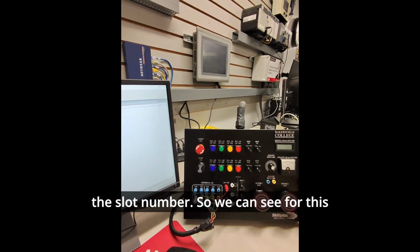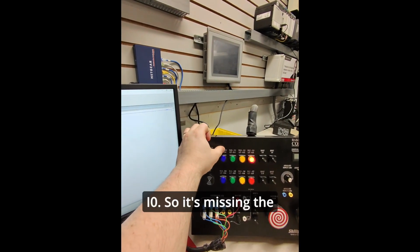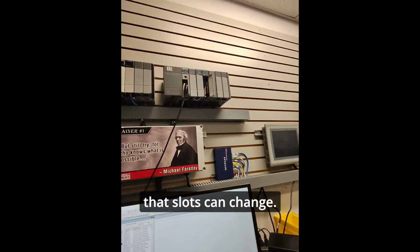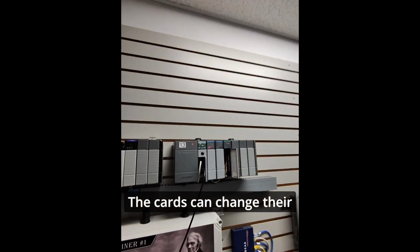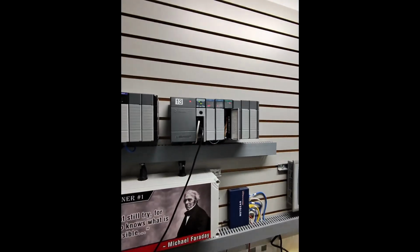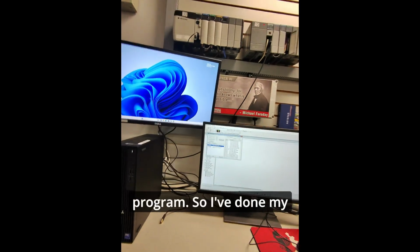So we can see for this first input here, we have I0, so it's missing the slot number. And the reason for that is that slots can change. The cards can change their position in the backplane, and that would change the slot number. So we have to convert that to the proper slot number within the program.